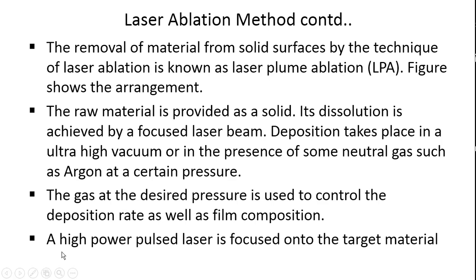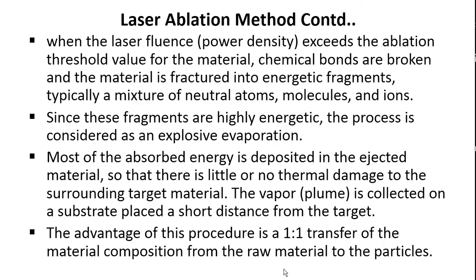Okay, pulse lasers are usually used for the laser ablation technique. That is what we have seen in the formation of nanofilms also. Pulse lasers are used. Okay. When the laser fluence, that is laser power density, exceeds the ablation threshold value for the material, the chemical bonds are broken and the material is fractured into energetic fragments, typically a mixture of neutral atoms, molecules and ions.